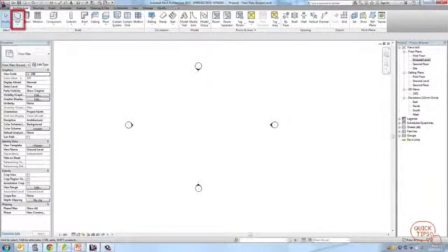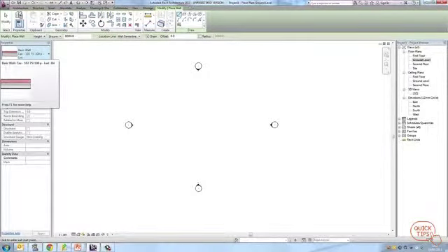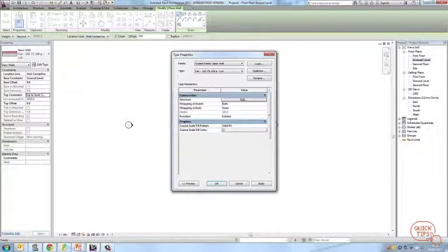So if you go over to the wall tool under Architecture, it has selected the basic wall cavity. This is selected by default. So we want to place a wall which goes up to, well, the constraint, we want it to go through first floor to the top, second. Okay, so you want to go through first floor to the second. Also, you can do that up here by clicking ground floor or second. So yeah, anyways, now